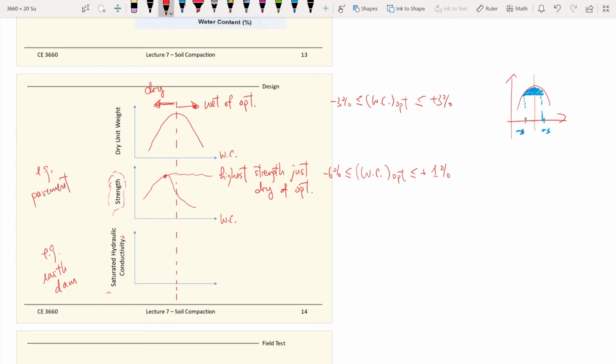You want the soils to be strong, to have a high strength towards the final grade before you get to the pavement that needs to sustain heavy traffic load. Then when you compact the last lift, you need to specify the water content,